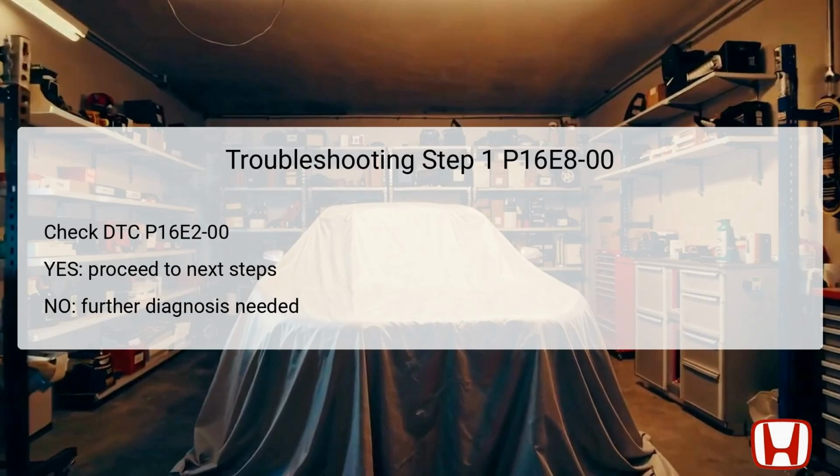In that case, the technician should follow the procedures outlined for P16E2-00. If P16E2-00 is not present, this could suggest that the issue is isolated to the shutter grille communication. Further diagnosis should be carried out based on the inspection outline provided in the service manual, and careful attention should be given to component functionality and circuit integrity.